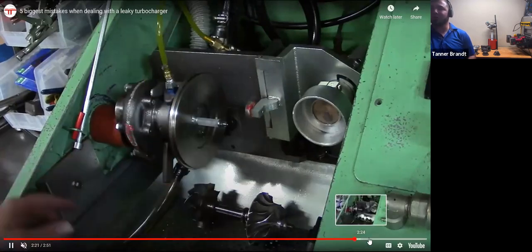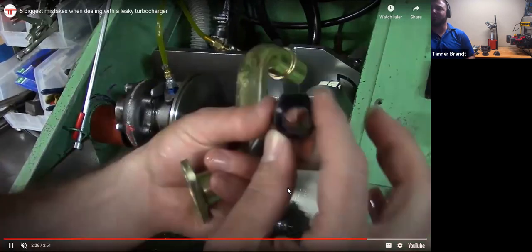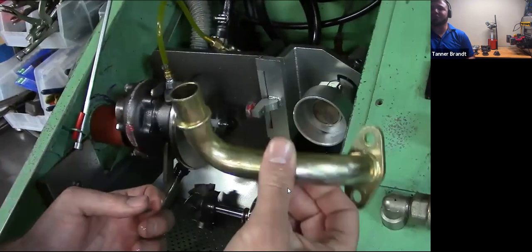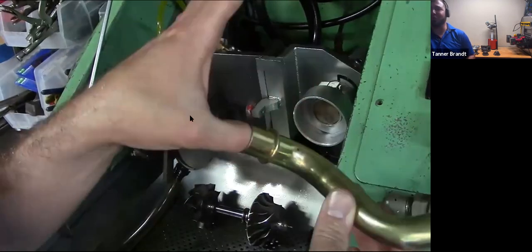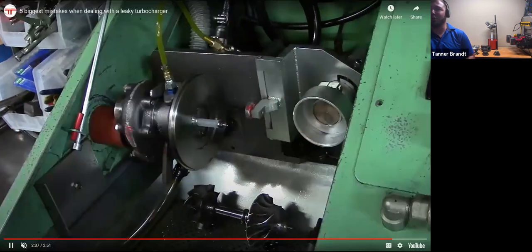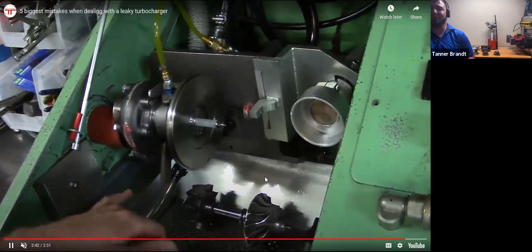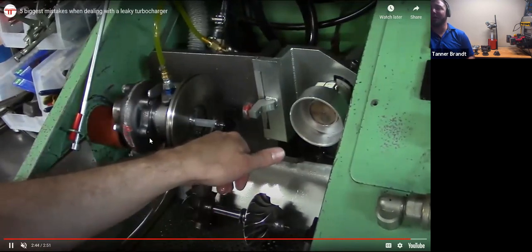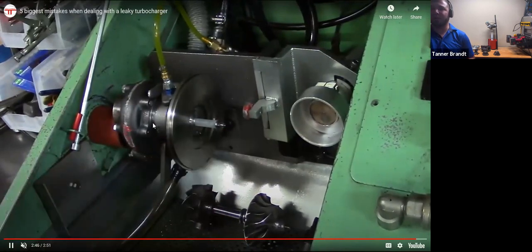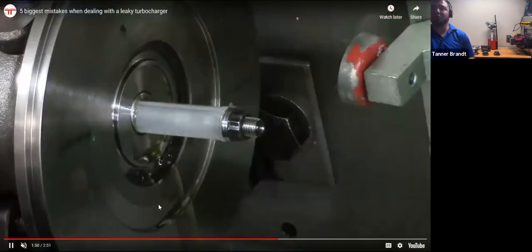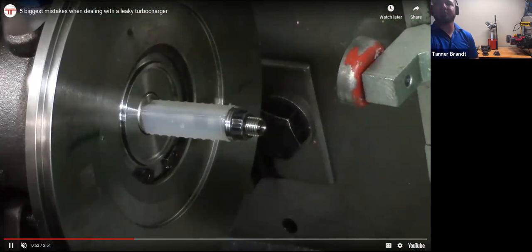So the other thing that can happen is people like to put these type of fittings in it. A lot of guys, the performance guys, will use those AN style fittings. They're not big enough. The flow for the turbo is determined and the drain tube is built for it. So if you switch to a different type of drain tube that doesn't allow enough drainage, now that bearing housing isn't going to drain out fast enough. So that's going to be potentially a big issue. So we'll talk about how that happens when we look at the bearing housing here.